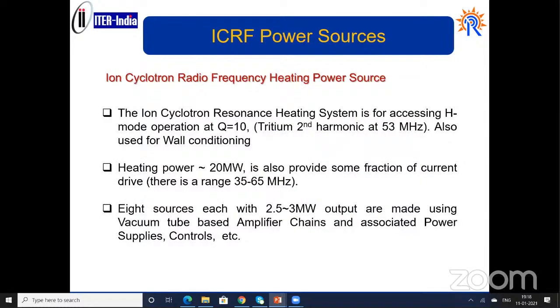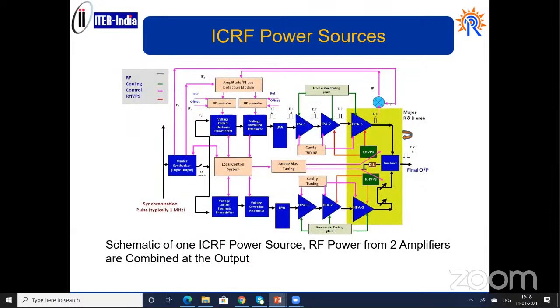That is the high stability mode of the plasma. Again, we are giving only the RF high power sources, along with the power supply, which comes in a different package. This is basically a big amplifier, starting from a very low power at different stages, going up to the highest level. The present technology gives an HPA output of only 1.5 megawatt. So we will combine these two branches of 1.5 megawatt outputs to get 2.5 megawatt continuously, and probably 3 megawatt as well. This is the design at the moment.